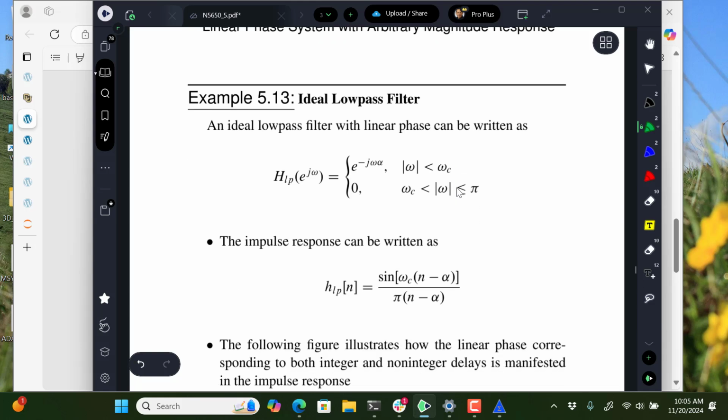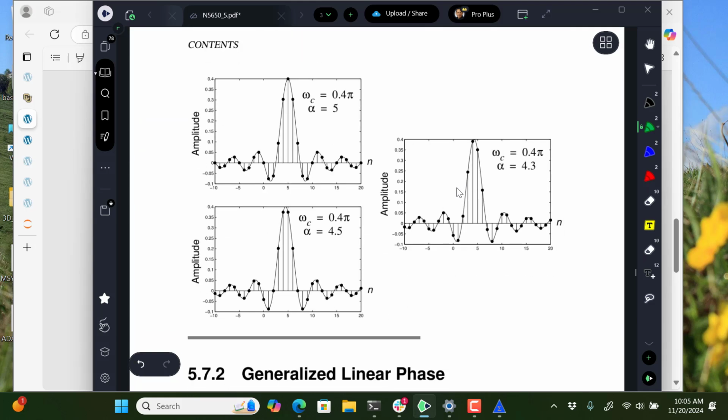So there's a lot of hemming and hawing around, getting motivated about how a sinc function could be ideal linear phase. The problem is it's got tails that go from minus to plus infinity, so we can't do that. But we can truncate it, and part of the motivation right here is that we're heading in the direction of this type of impulse response, but we're going to chop it off so that if you chop it off, you can slide it over and not have any tail for n less than 0. That was a concept from the very beginning, right? Causality.